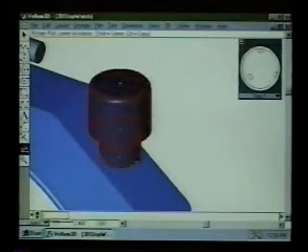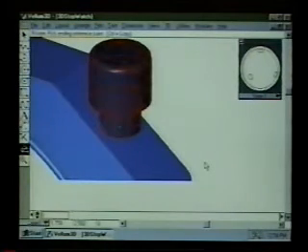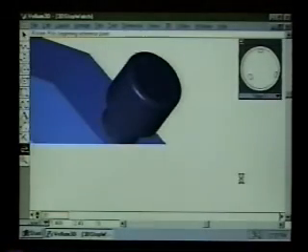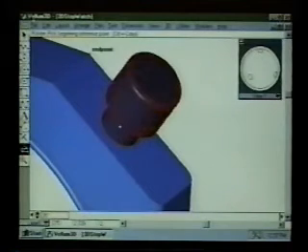And so now I can come in here and again highlight this, or just brush the edge to wake up the center, go to the center, because that's going to be the pivot point of the rotation. And then come out onto this end point, because that's the beginning point that I want to grab, and then come to a point on the surface, which will be, for example, down here near the end of this part. If I come right to that midpoint or that perpendicular point on the face, that will give it the ending angle to go to, and now it will be rotated into position. And there it is, rotated in position. And we're done with that.